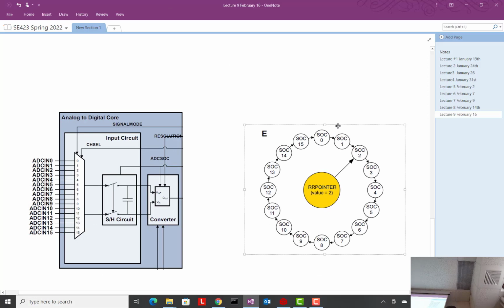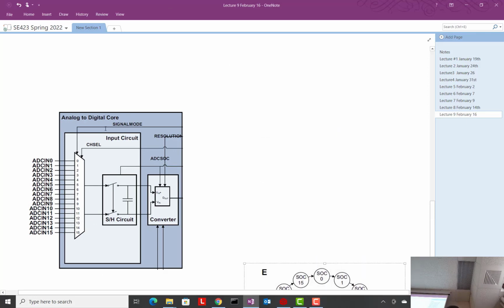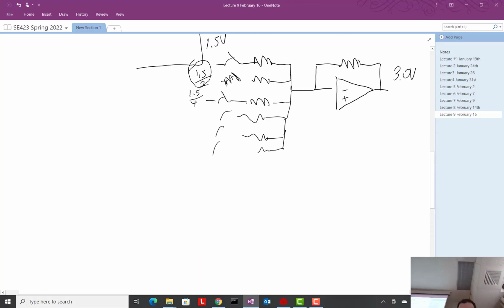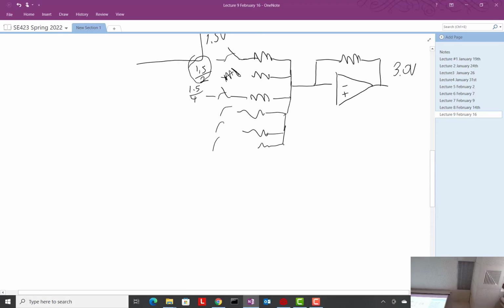Again, I do not want you to understand all the details of an ADC. I know I don't understand all the details. The reason I want you to see what's going on inside the ADC is for you to realize that it's not immediate. When you tell an ADC to convert, it's not done a couple of nanoseconds later. It's done maybe half a microsecond, more like a microsecond later, not a nanosecond. So it's not immediate.